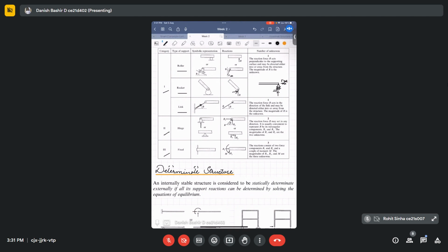So we can have Rx and we have Ry. One support reaction, one axial reaction. Another commonly studied joint is the fixed support, as in a fixed beam. In a fixed support we have one axial reaction Rx, one vertical reaction Ry, and a moment Mz is also developed like this.